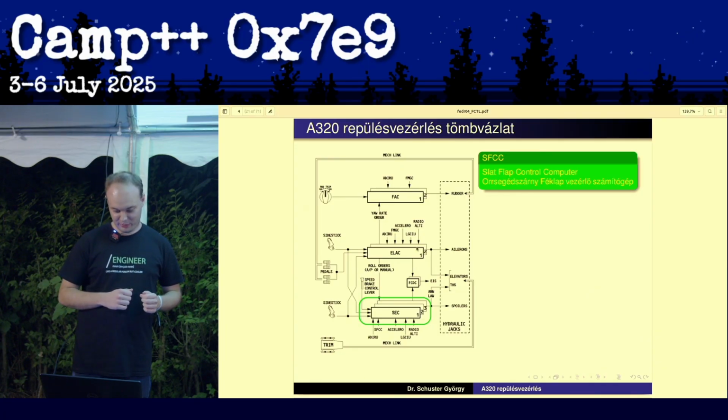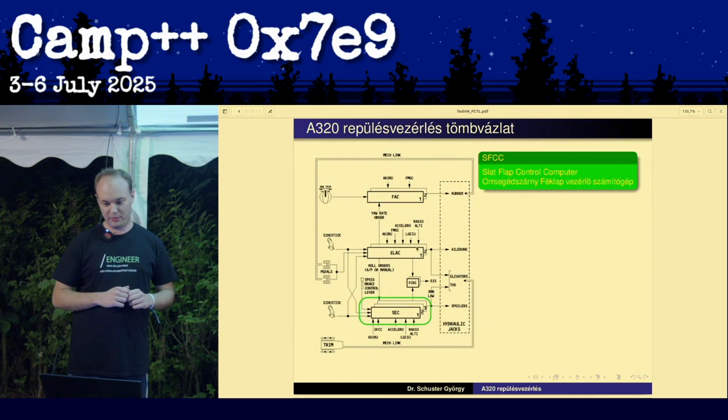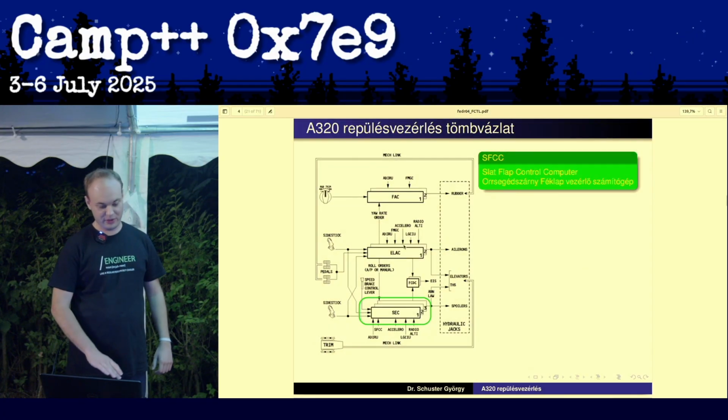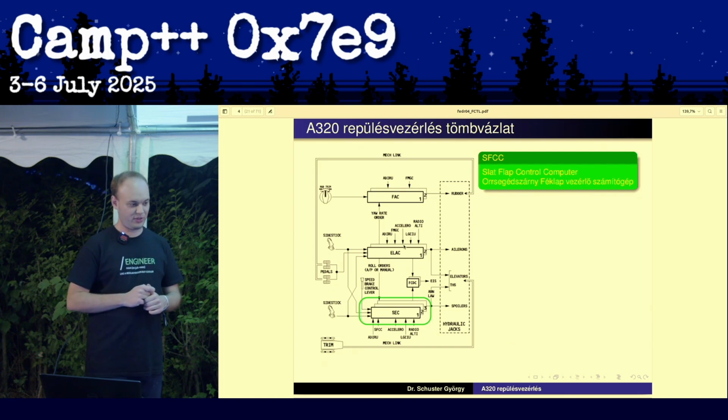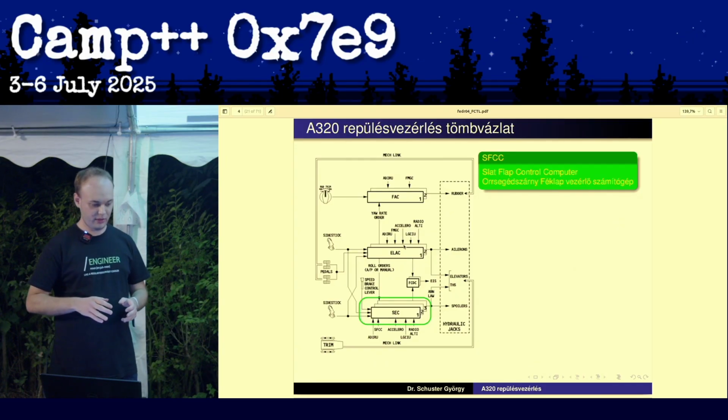And the problem there was that even if you're flying the aircraft manually, you can't just simply override this. So in that case, the only option you pretty much have left is a cutout switch for the trim motors that you need to use to shut off the motors.